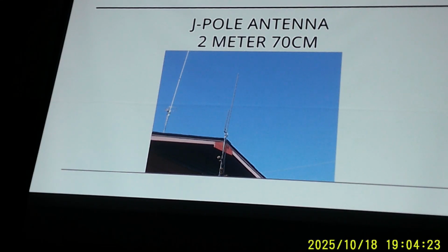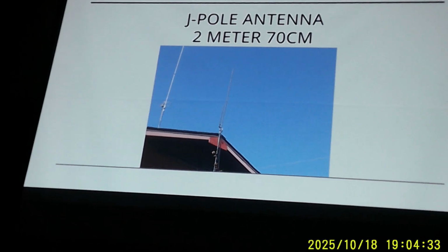Part of your radiating line is your coax. The problem with that is it also radiates quite well into your shack if you don't put a balun or something to cut it. A choke. In other words, you want to block the signal from getting into your shack.